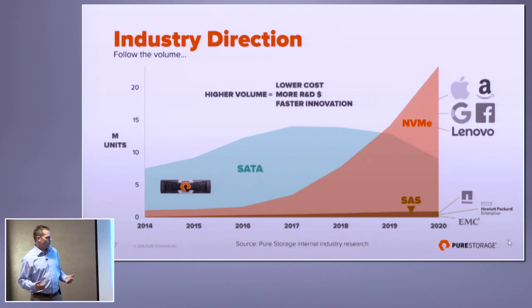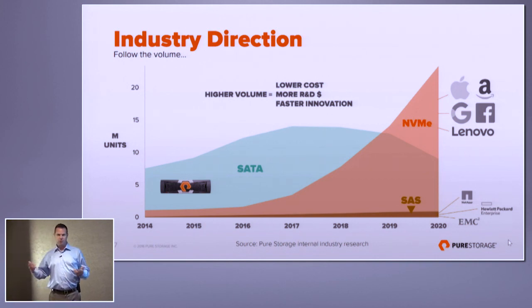The thing you get from SAS is typically that it's dual ported, and other aspects of it give you higher performance and high resiliency. So NVMe can go there and cover that segment. For SATA, it's usually cheaper. I think probably half the people in this room with a laptop do have an NVMe M.2 form factor, kind of gumstick form factor, inside. And so you can cover the entire market with this technology. You just optimize for the different segments.